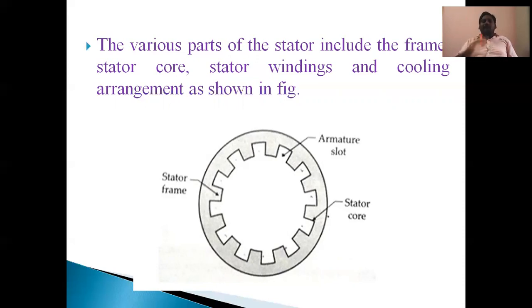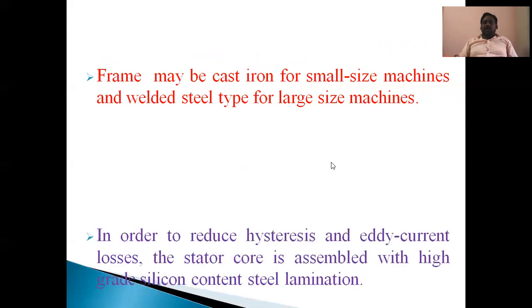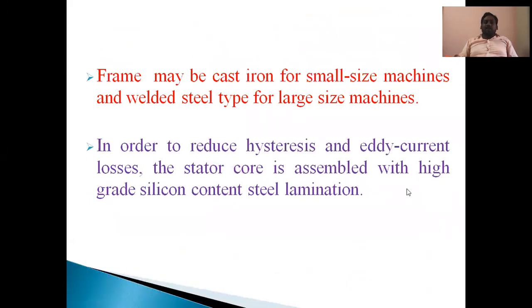That's why, to avoid this problem, the stator core is laminated with steel. The stator core is laminated with high-grade silicon steel, to reduce hysteresis and eddy current losses. To reduce eddy current losses, we provide laminations.